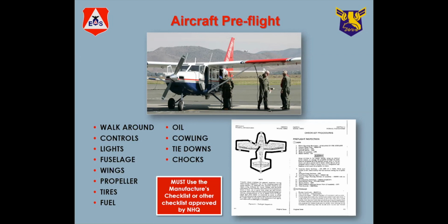1 or 2 PSI short or over can have a severe impact on the handling of the aircraft on the ground. So it's important to make sure that you stay on top of that. A good idea is to make sure there's a pressure gauge somewhere in the aircraft so that check can be done consistently before and after you fly.